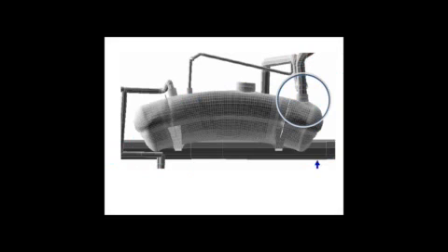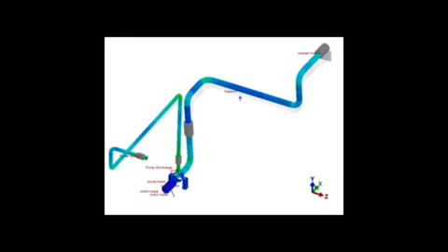If you have this model in FEA Tools, or if you have this model in Caesar and you run FEA Tools, it will let you build this connection and analyze it properly for flexibilities and stresses. Here's a good example, because this is a pump.